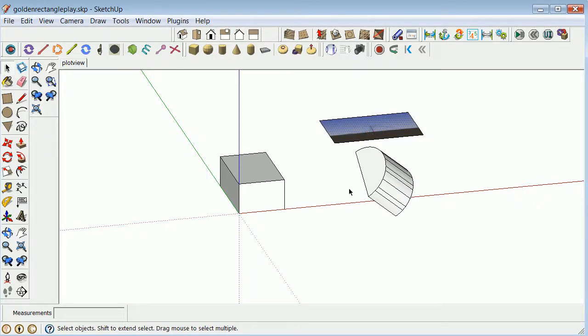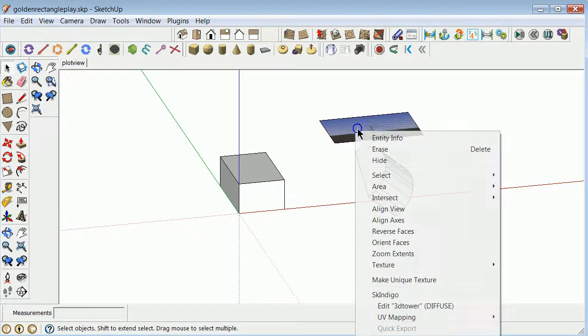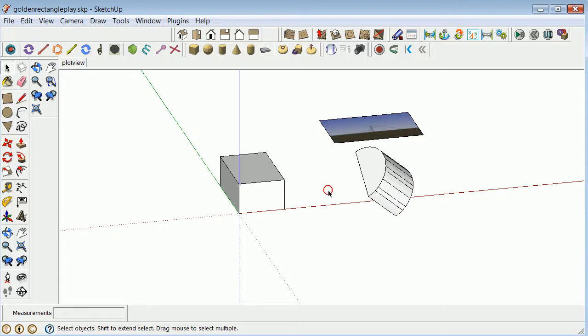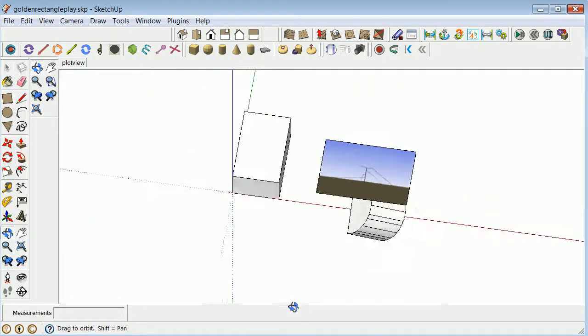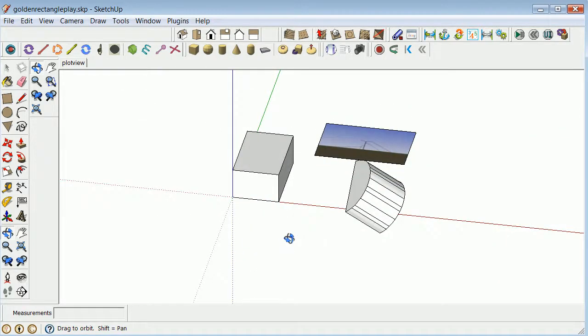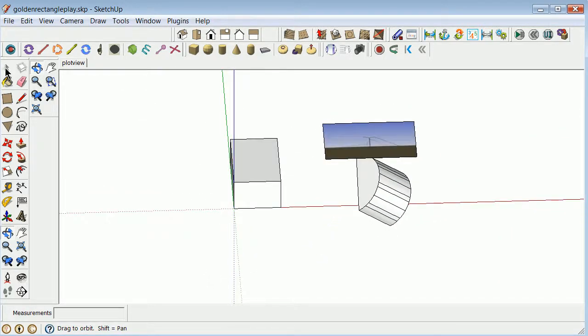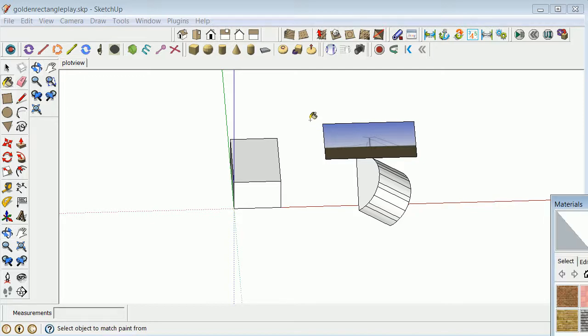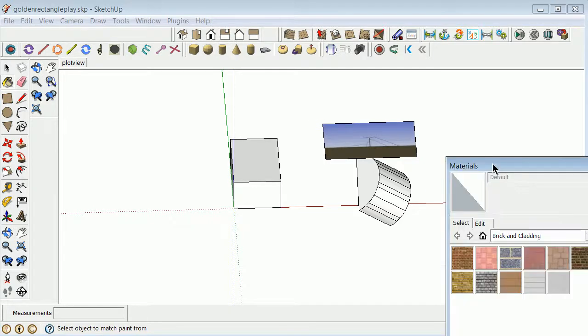And now it becomes something that can be, I'm going to right click on it and I can look at the texture, and I want to see that it's a projected texture. Right, that's what I'm looking for, a projected texture. Very often it should be related to what you're doing. It might be a design, it might be something from Photoshop. Now what you're going to do is this. If you're working on a Windows machine, you're going to go to the texture tool more or less there, which is the paint bucket. And you're going to suck up the texture.